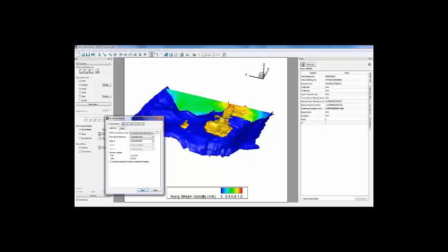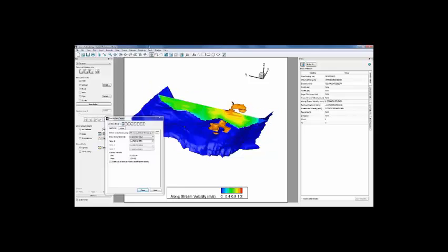These, of course, the ability to probe any point means we can do calculations of other parameters. So you've got this list of along-stream and downstream velocities. We have our X, Y, Z velocities, but that gives the potential to calculate a lot of other parameters that may be important to what I'm doing. One thing that comes to mind is the kinetic energy flux, which is the available power. So if I'm looking at hydropower generation, I now have the ability to look throughout my reach, my cube, and say, where do I have the greatest power available? In particular, some of the small-scale hydrokinetics that are being talked about.